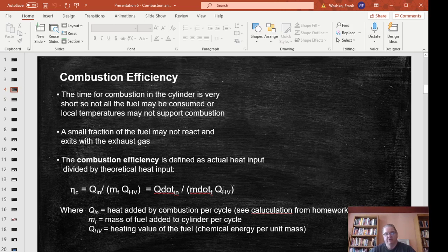fuel air mixture burns, how quickly it burns, whether it burns completely or leaves pockets where it's unburned, things like that. Like the problem we did where we looked at where it initiated, how long it takes to get to the outer edge of the chamber, how long it takes for combustion to complete fully, whether it will complete fully on one side but still be trying to burn on the other side. So the combustion chamber design itself is going to determine combustion efficiency, how much heat you get out of the fuel, whether you burn all the fuel.